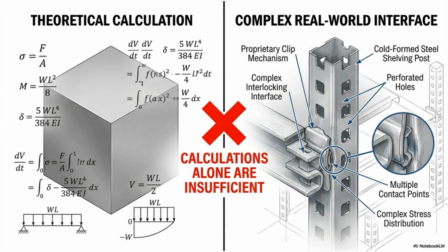The equations are well understood: stress, moment, deflection. But proprietary clip mechanisms introduce multiple contact points, complex interlocking geometry, and non-uniform stress paths through perforated cold-formed steel. At that interface, theoretical calculation alone is insufficient. This is not a gap in engineering. It is the reason testing exists.